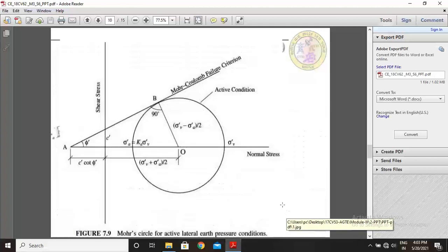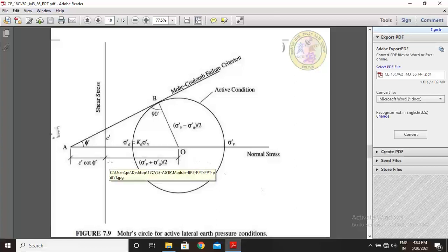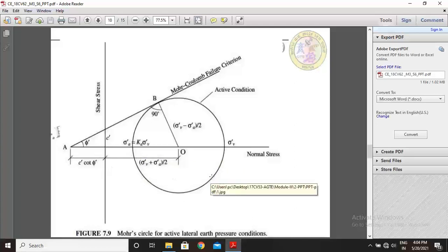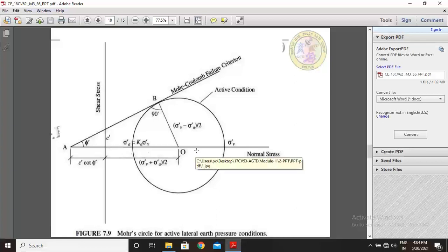Based on our equations, we have plotted the Mohr circles for the given values. This is the most important concept, explaining how to plot the Mohr failure envelope. From the origin we select the distance x, and with this distance we select the radius and locate the point O. This is point B, and this is the radius, and we plot the Mohr circle and locate the tangent point.